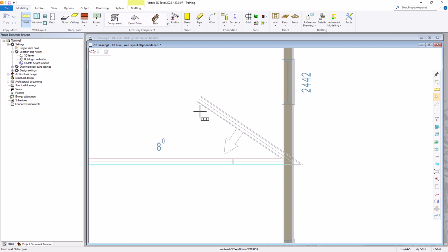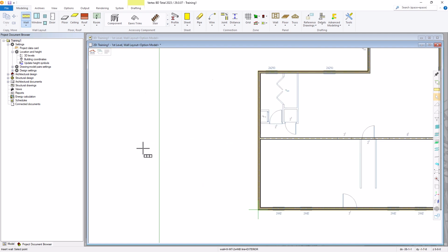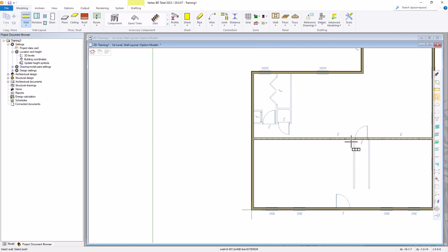Once you're done adding walls and you have a link wall still on your cursor, just hit the letter V to verify, meaning that you're done with your selections. That's all you want to add. And it will clean up any intersections on both ends and insert the wall.